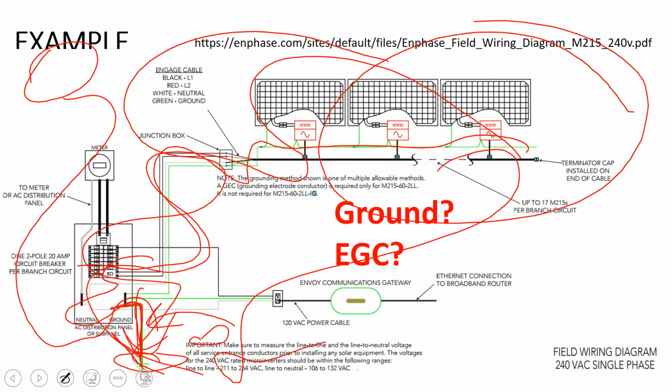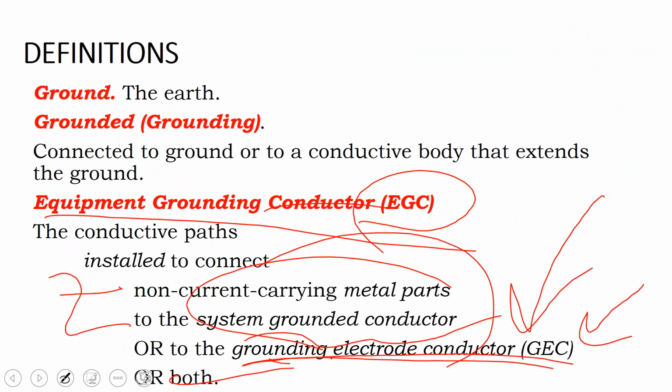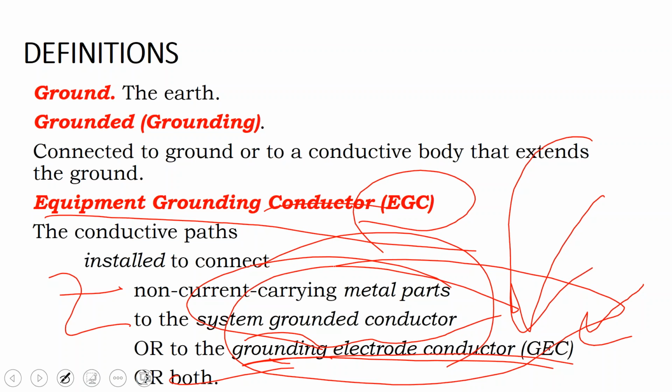Like if you're doing a DC system or an AC three-phase system, it may be that your DC grounding requirements require a thicker cable than AC does. And so sometimes your path to ground can be subject to special grounding electrode conductor rules, or your equipment grounding conductor is not really doing anything more than saying, well, you have metal parts on your system, like the frame